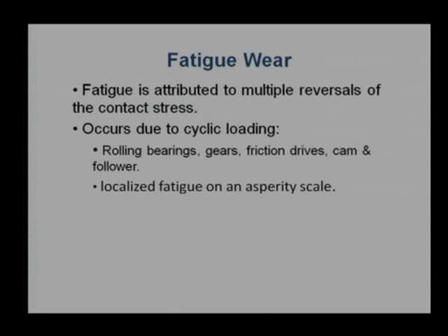And 99.9% of failures occur because of contact stress. Fatigue bending does not cause much failure. The factor of safety by and large is almost 3 to 4 in bending, while for contact stress the factor of safety turns out to be 1.4, 1.5. The same holds for cam and follower mechanisms. Rolling fatigue governs the overall wear mechanism.